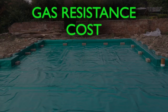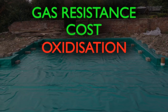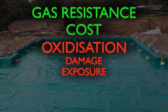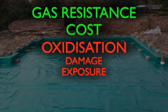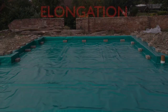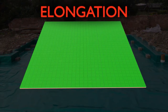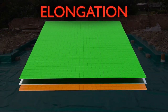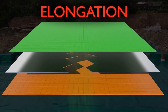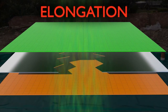The first problem is reduction in performance over time caused by oxidisation of the foil layer. This can either be caused by damage to the membrane, by exposure to chemical contaminant levels out with its design specification, or at the edges of the membrane where the foil is exposed. Another problem is common on all sites where foil membranes are used, regardless of the presence of VOCs. While the base plastic membranes are able to elongate to some extent, this is not true of the foil layer within them. If settlement occurs, the corresponding stretching of the membrane can rupture the foils, leading to a significant deterioration in the gas barrier performance.